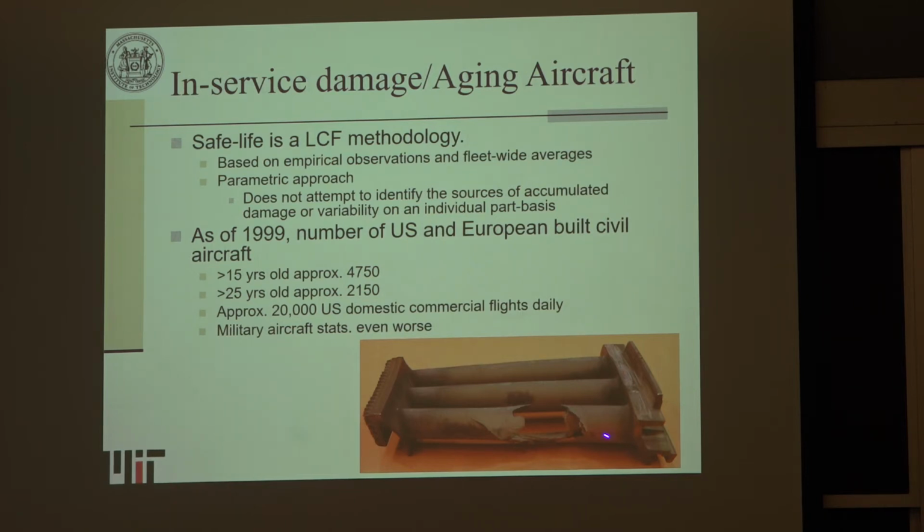But this is one of the reasons why the FAA has gone to the safe life methodology. It's based on low cycle fatigue. Low cycle fatigue ties into trying to design against a brittle fracture mode.